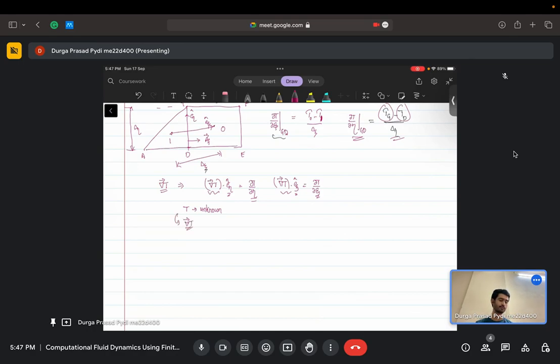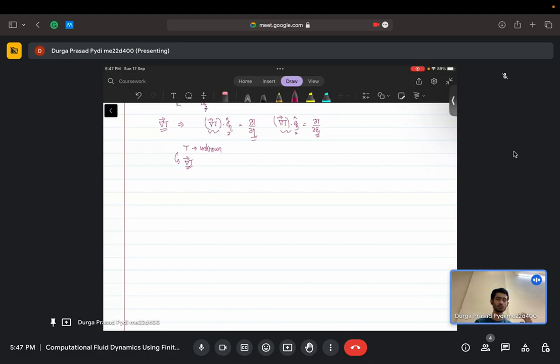So the way we solve this is using something like our relaxation schemes, which we have used in source term linearization, where since you do not know the value of gradient T, you will assume the value of gradient T from the previous iteration as your current gradient, and then you proceed ahead.